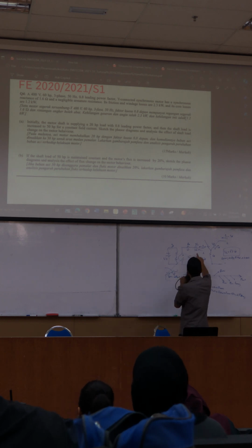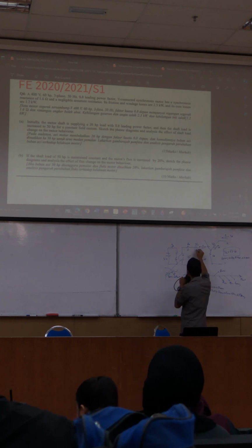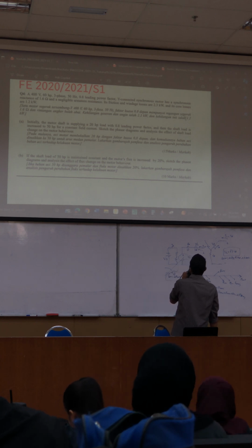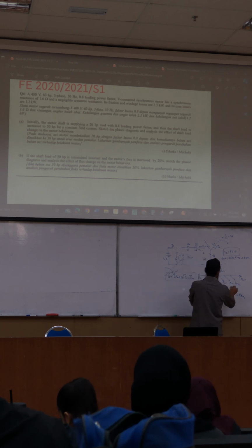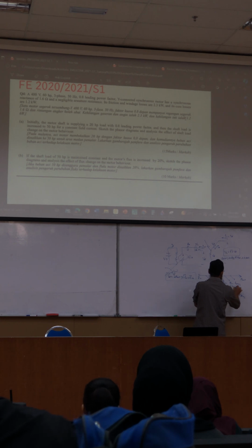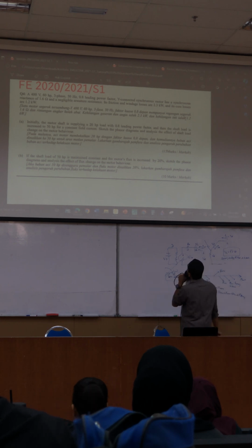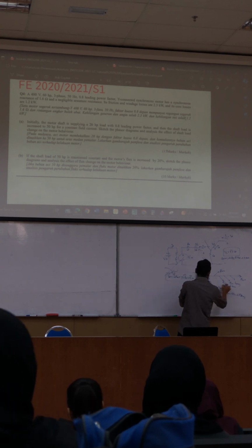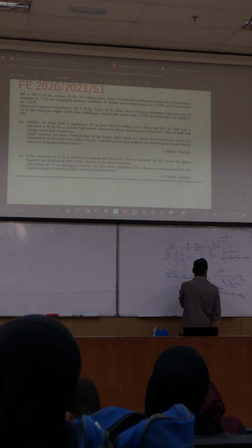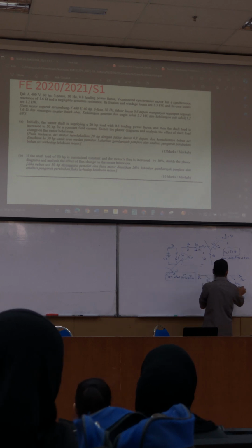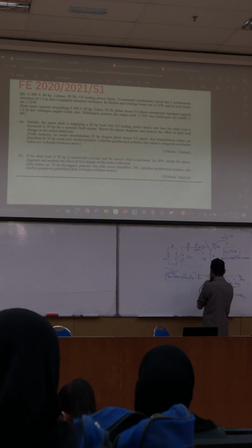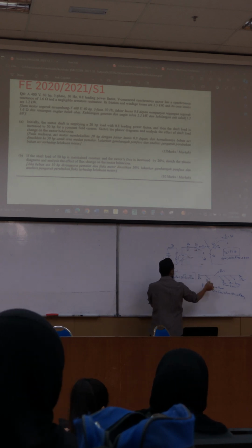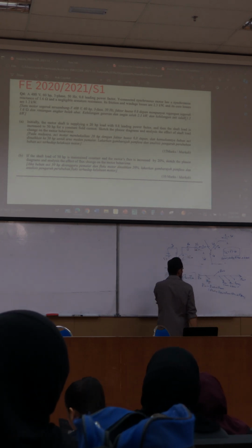Okay. What else? Friction and windage 2.3 kilowatt. Core loss 1.2 kilowatt. Stray loss 0, it's not mentioned. Electrical: you have I_A R_A with R_A 0, so electrical will become 0 as well.